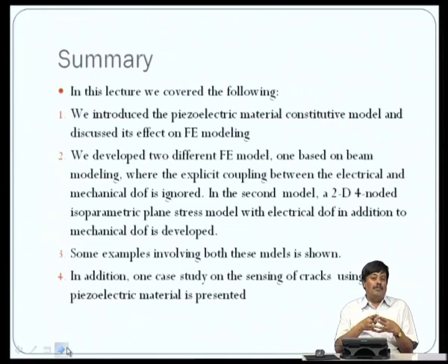If you are modeling a thermal problem, then the temperature and the temperature flux will be the dependent and the force variables. So, like that, any physics of the problem we can use. If we are solving a fluid problem, we need to idealize the whole Navier-Stokes equation into finite element modeling, where instead of displacement we will have velocities as the basic degrees of freedom. So, it depends upon the physics you are modeling.